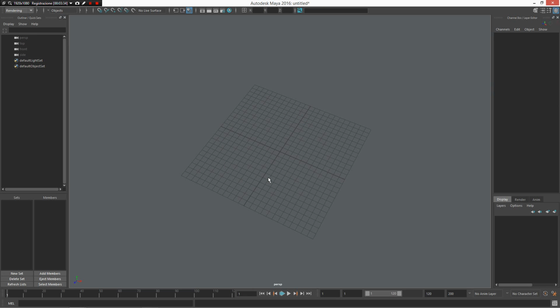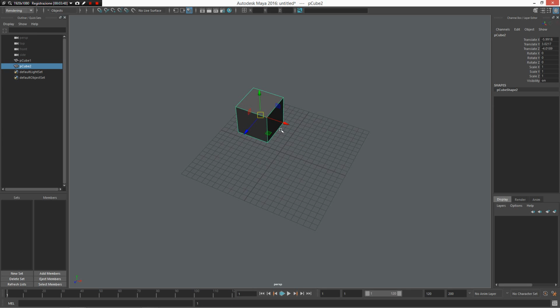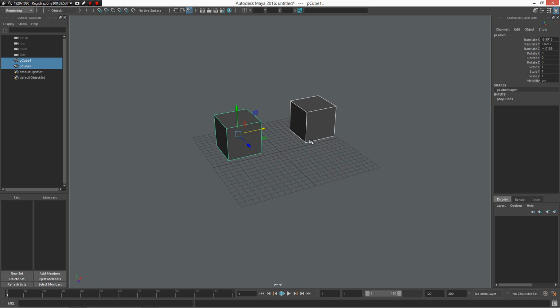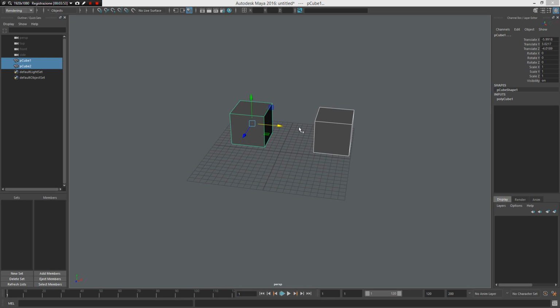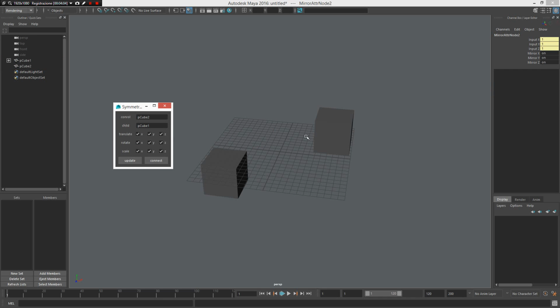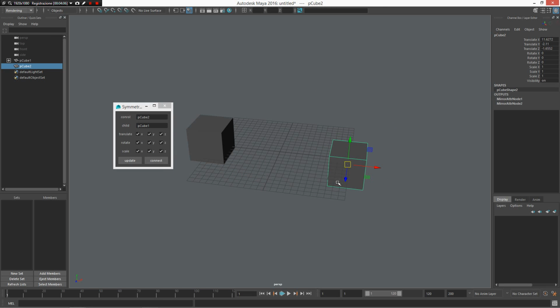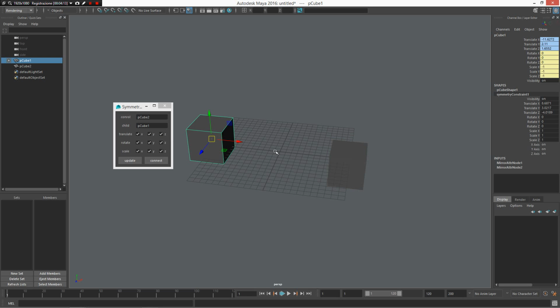Another script, in this case another plugin made in Python by Andrei Meniskov, is the symmetry constraint, as you can see early in the README file. I can create a poly, duplicate it, and from here I can select the two objects and press Z with the left mouse button, choose symmetry constraint, and update my selection. So in this case, cube 2, control cube 1, connect. I have my symmetry already connected to my objects. Very powerful system, very smart system.